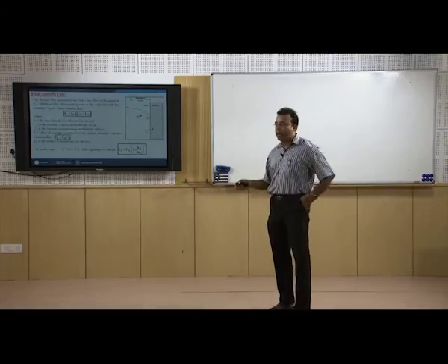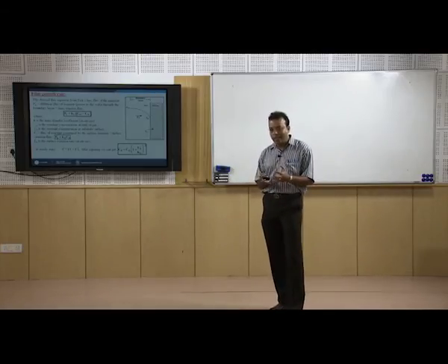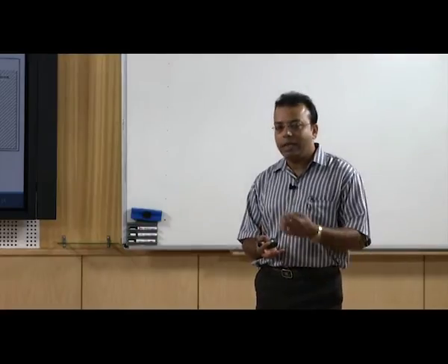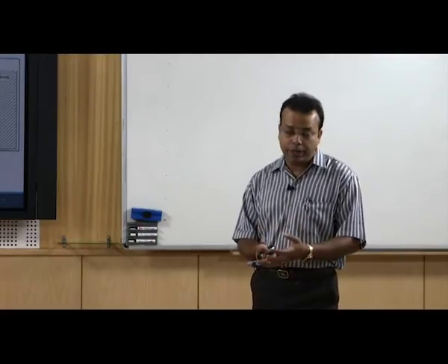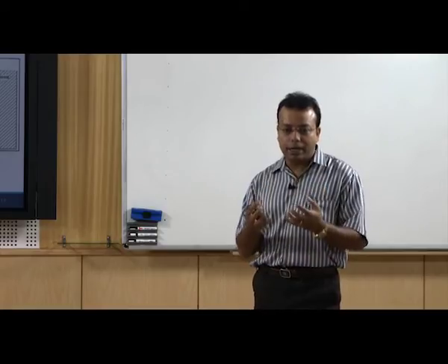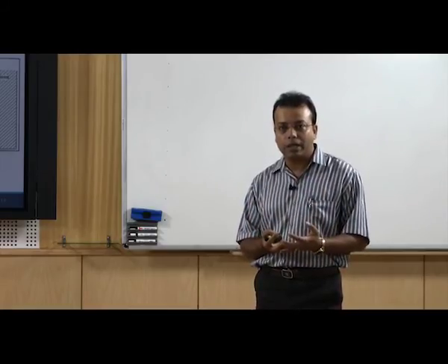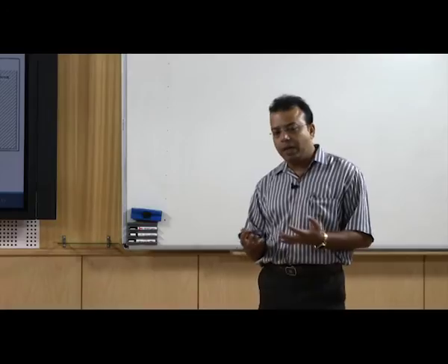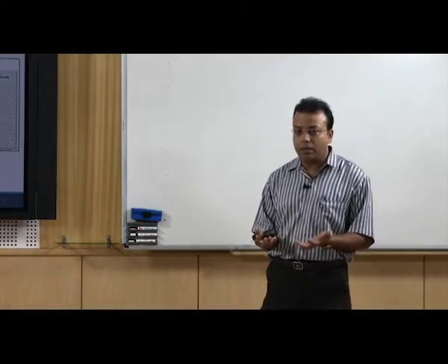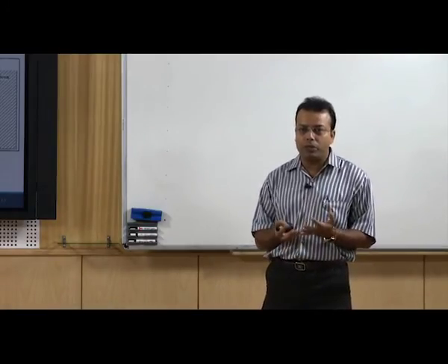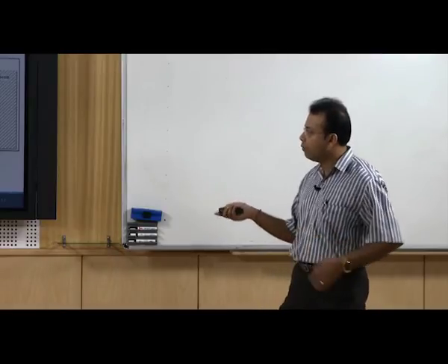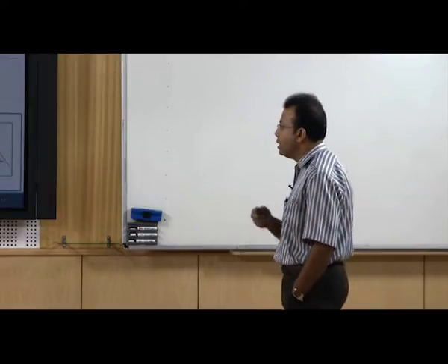So, depending upon that we can increase or decrease the gas flow rate, or maybe the energy we are applying to the target itself. So, there are lots of input parameters by which we can easily control the film growth rate onto the substrate itself.